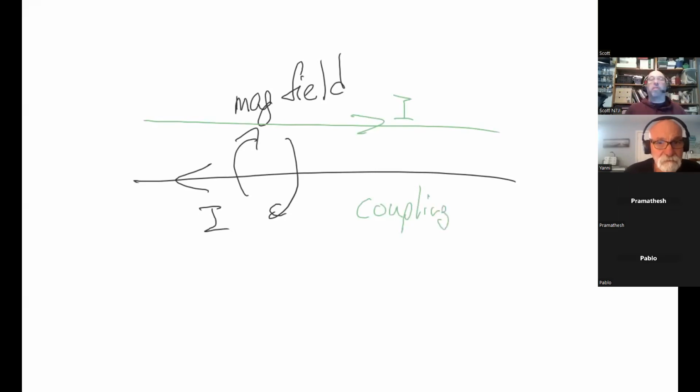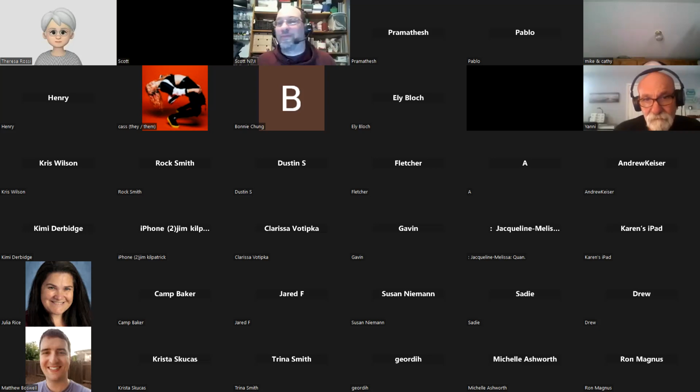And what if those are microphone wires? Feedback. You get crosstalk and feedback and all kinds of bad stuff. So in order to prevent that, we use shielding. That's why, for microphones, we use shielded cable. The shield basically creates an environment surrounding the stuff on the inside that essentially catches the magnetic field and constrains it internally. So that's why we use shielded cable.